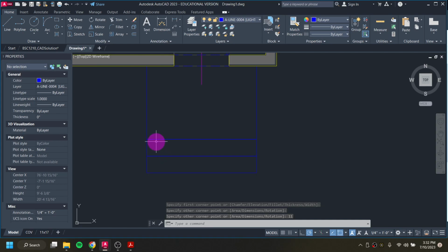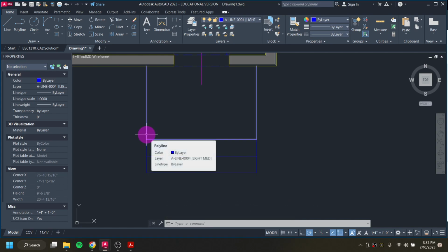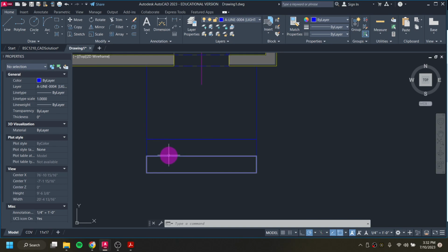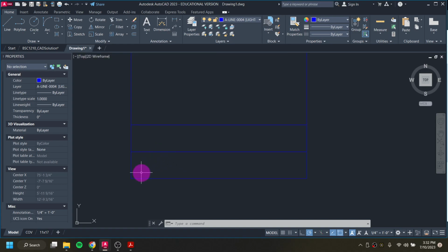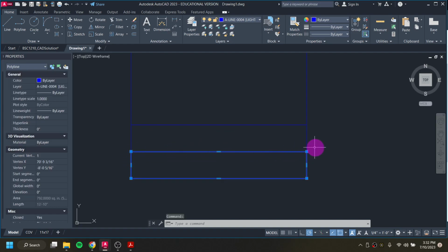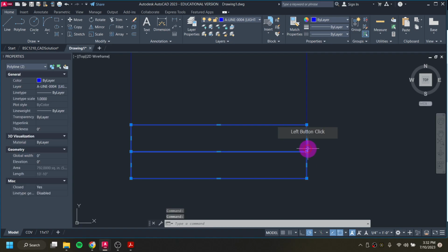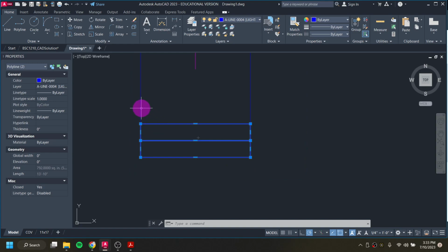And one thing that could be a problem, in this case it won't be, but if we were trying to laser cut it, it wouldn't necessarily be a problem, is we do have overlapping lines. What I mean is here we have a line from this rectangle going across, but this rectangle also has a line sitting there. If I sent this to a laser cutter, it means that it's going to go over that spot twice, which could be a problem. And we also have the same thing going on up here.